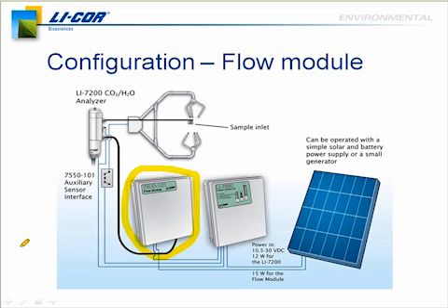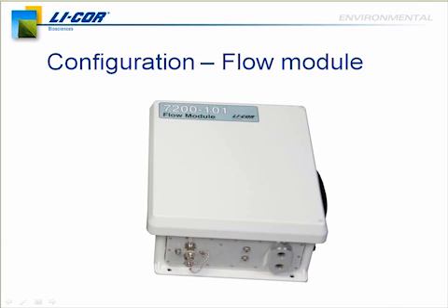And what that is, is a precisely controlled flow. The user can select the flow rate that you want, again through the Windows interface, and then there's active flow control. So the module is going to monitor flow consistently, and if there's fouling in the filters or if anything is happening, it will automatically feedback and make sure that it maintains the flow rate that you've asked for.